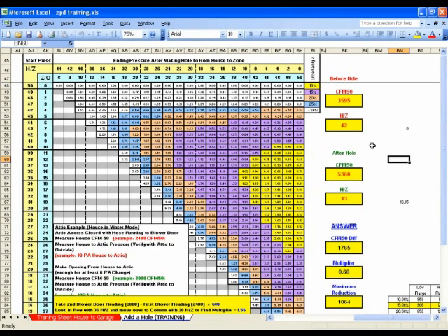With this one we have 4 numbers we need to enter in. The numbers in red here again are the numbers that we need to enter in. Our CFM before adding the hole, our house to zone before adding the hole, our CFM 50 after adding the hole, our attic pressure number after adding the hole, and then in the spreadsheet again it calculates the difference between CFM before and CFM after, and then our multiplier to figure out our maximum reduction. And to get this multiplier number, we'll look at numbers going down this way are our starting pressures.